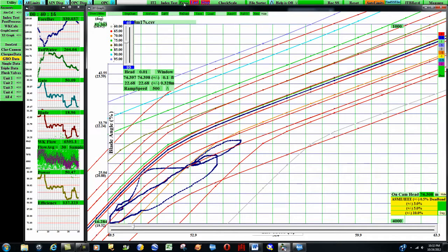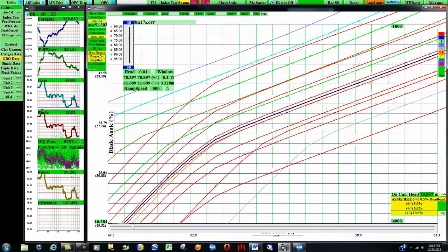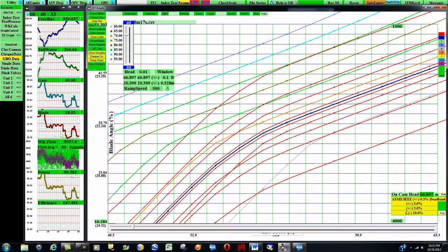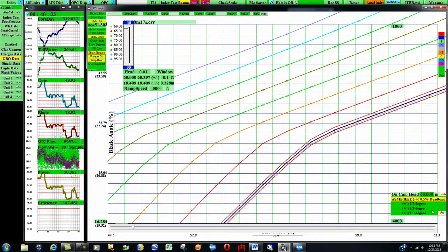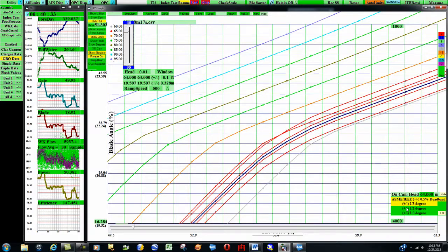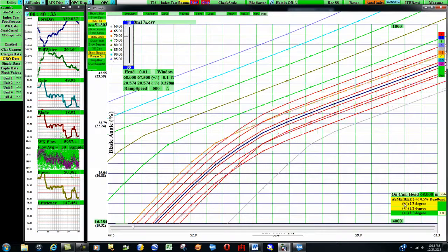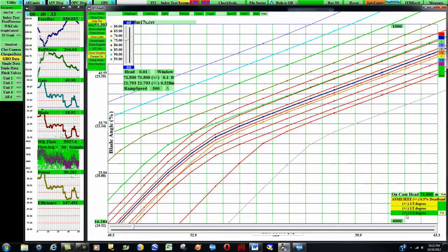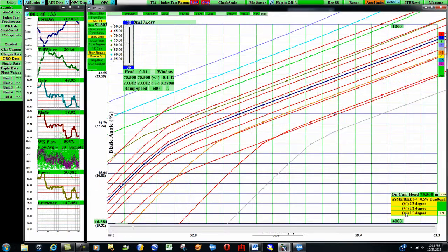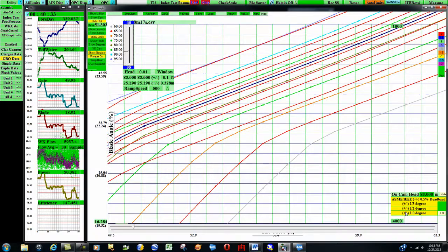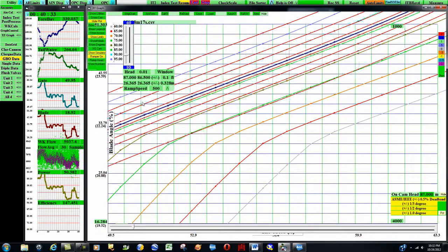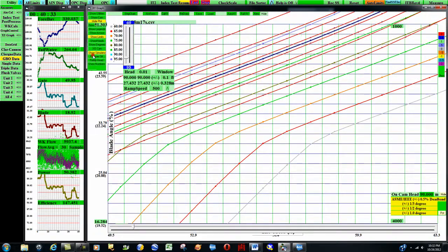Clicking on the degrees button calls the gate blade optimizer added deadband limits. These are at 0.3, 0.5, and 1 full degree. The first three were added by the Hydro Design Center to mask the inherent dynamic instability in their 3D cam and blade controller design. The 1 full degree limit was added by the Walla Walla district to make certain that the instabilities were completely masked in order to avoid over-exercising the turbine blades and prevent premature trunnion bearing wear.